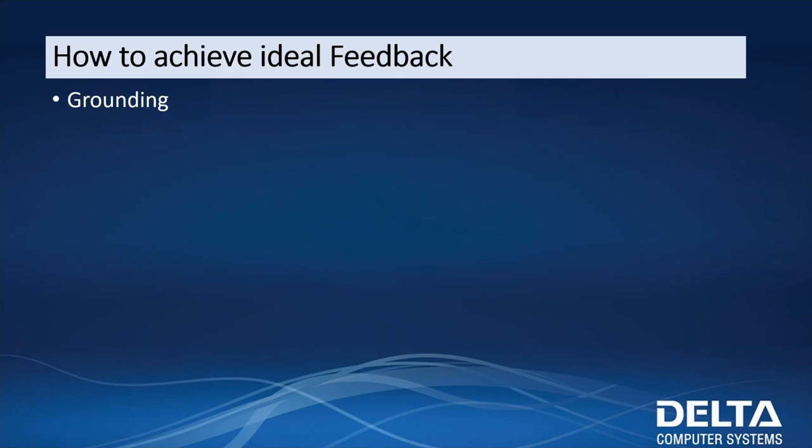Sometimes it's just very noisy, but you really want to make sure that you are grounded, or you'll be fighting with phantom problems, and you may be able to get something that's controlling, but that's always the first thing we check if you're seeing excessive noise on your feedback. Check your grounding. Shielding is important as well. Make sure your cables are shielded so they're not picking up all that electrical noise that's going on, especially in an industrial environment. If you're close to a motor or something, make sure that your cables are shielded. Also, having twisted pairs is a wonderful way to reduce that noise.